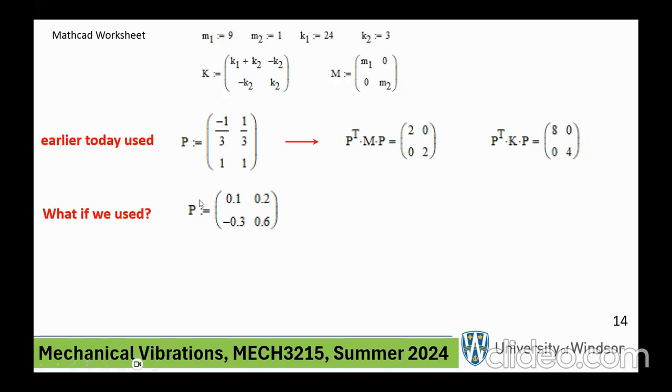What if, for example, hypothetically, for U2, I used 0.3, I get a U1 which is 0.1, etc. So what I'm saying is that I arbitrarily found this modal matrix because the choice of the mode shape was arbitrary, entirely arbitrary, okay? Instead of 1 for this, I could have chosen negative 0.3, and of course, if you do that, you're going to get 0.1 up here.